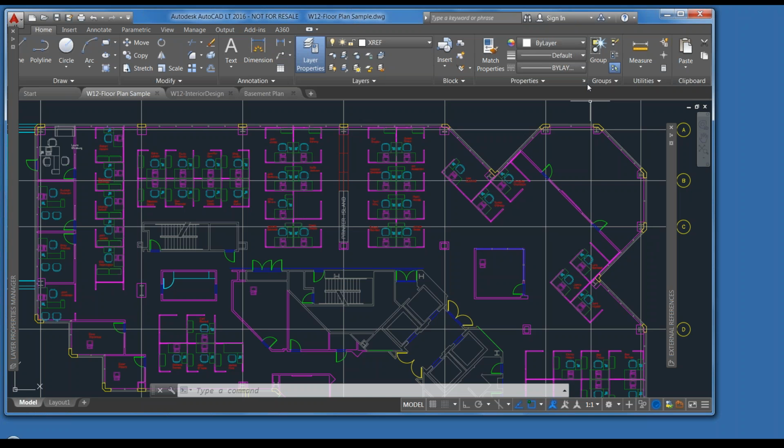And then, of course, another benefit is if someone else is working in these drawings at the same time and saves the changes, you'll get an automatic notification that X references need to be updated. So with that quick review and a basic understanding of how X references work, we can start thinking about how to use them strategically in your business to help your workflow and do things more efficiently. We're in AutoCAD LT here, and so all of these examples are flat 2D drawing examples, but the same principles really apply to 3D drawings.